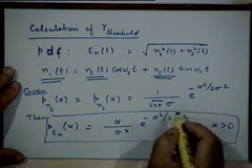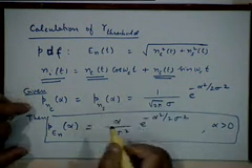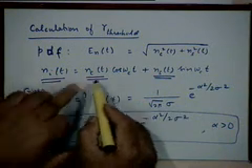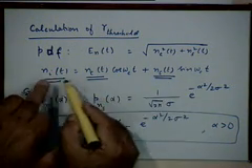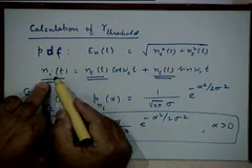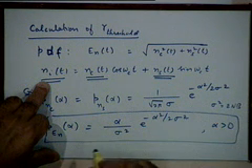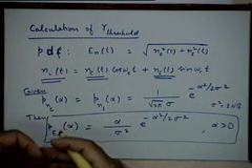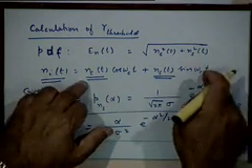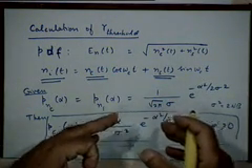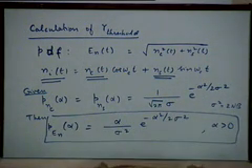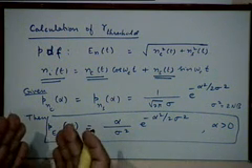Okay. Incidentally, what will be sigma square in this case? Sigma square is the noise variance of N_c or N_s. That will be the same as the noise variance of N_i, and what is each of them equal to? 2N_B, if you remember, isn't it? This is the noise variance of the narrowband signal which is coming out of the band pass filter before the envelope detector, right.